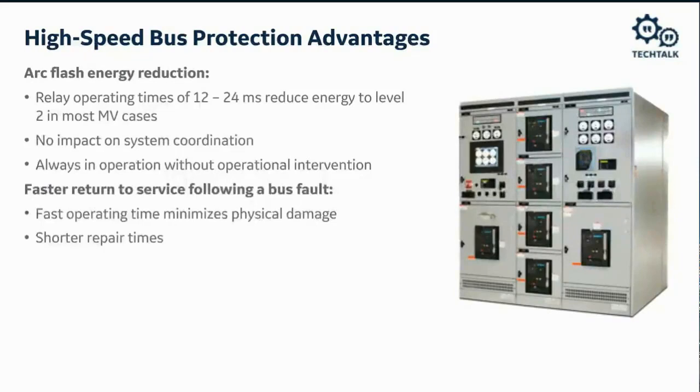One of the other advantages of using bus protection is that it has no impact on system coordination issues. If you attended the previous overcurrent seminar by my director, Terry Smith, you would have seen that coordination can add significant tripping time to our schemes. Bus protection is always in operation, and coordination studies are not required to set and select bus protection systems.